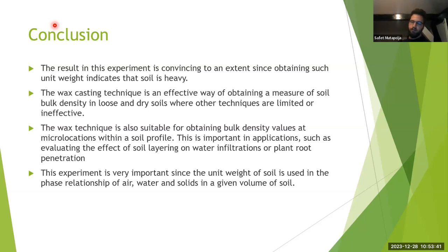It's usually important to remember it's harder to do compaction on plastic soil than on elastic ones. And we're going to speak about Atterberg limits. We spoke about that before. If you remember Atterberg limits and the soil phases, you have a plastic limit. If your plastic limit is higher than 30 or 50, in the worst case scenario, it's going to be super hard to do compaction on that soil.